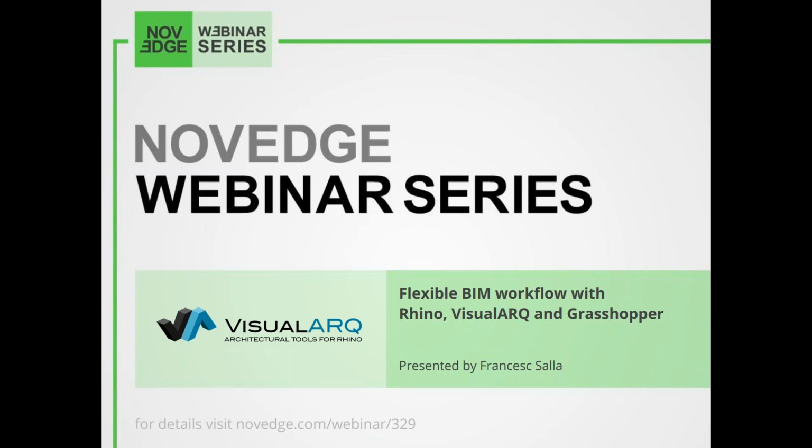You will see an overview of how to work with parametric architectural objects, how to produce 2D drawings from the 3D model, how to generate dynamic BIM objects driven by Grasshopper, how to automate many modeling tasks through the VisualARQ components built for Grasshopper, how to add custom data to geometry, and listing schedules, and finally, how to deliver BIM models and collaborate with other tools through the IFC import-export capabilities. So a webinar packed with content.